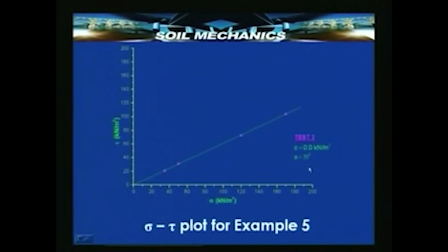This means that this soil has got a slightly lower angle of internal friction compared to that soil and is therefore having less strength. Note here one important point which I stressed earlier, that is the scales for sigma and tau have to be the same. If they are not, we cannot directly read out the angle here and take it as angle phi.